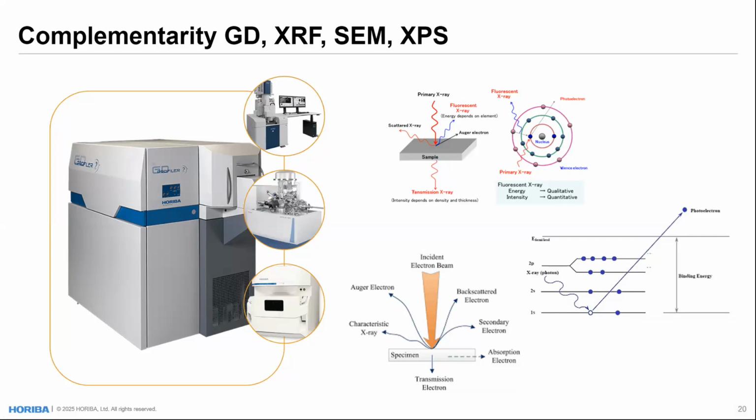We're going to switch gears and talk a little bit about the basics of X-ray fluorescence. You probably know this from EDS, but there are two versions of the fluorescence technology. One is EDS, which is electron beam excited, and the other is ED-XRF, where we excite the material with an X-ray beam. Both generate the same fluorescence X-ray.